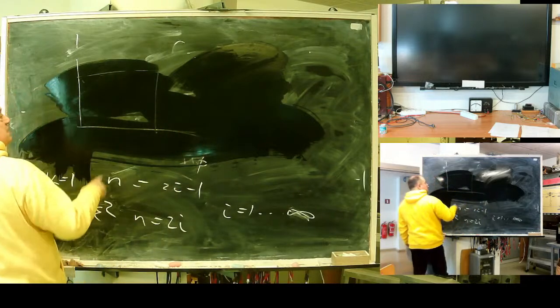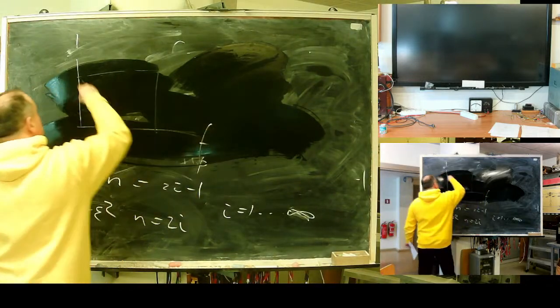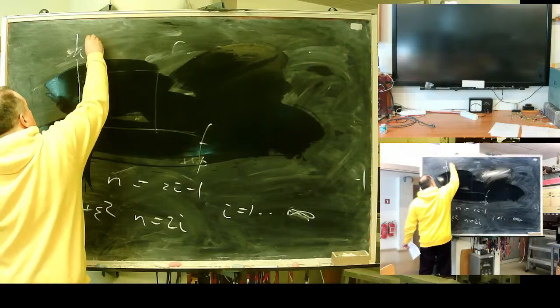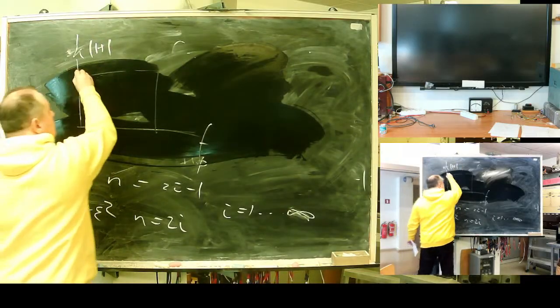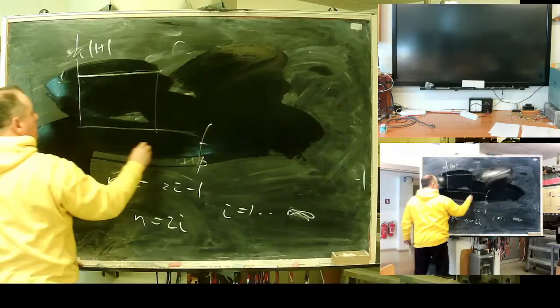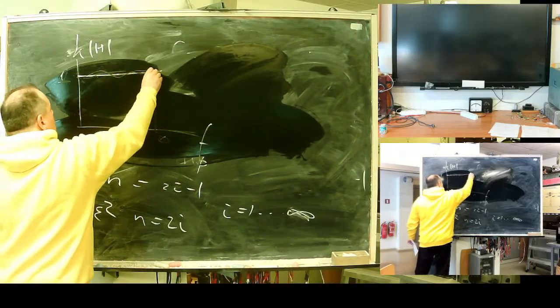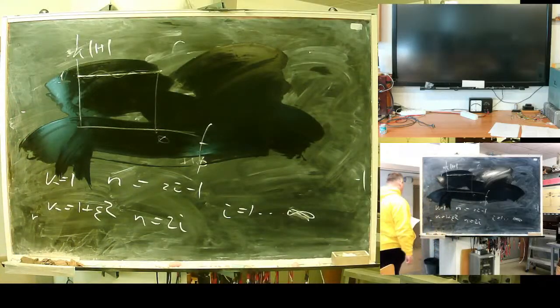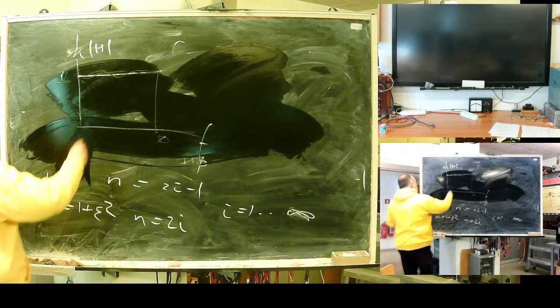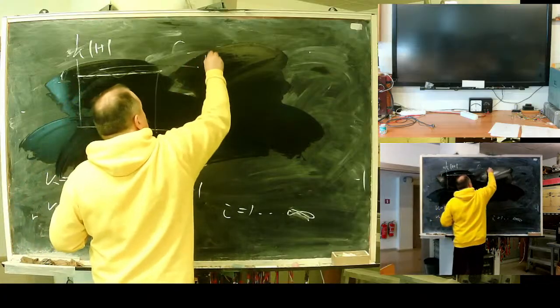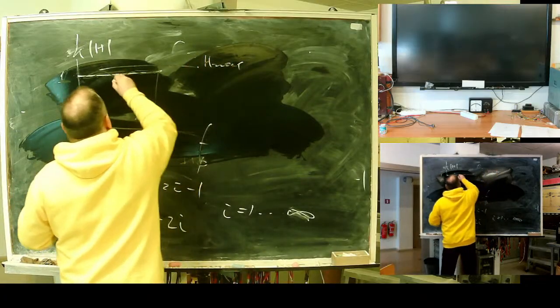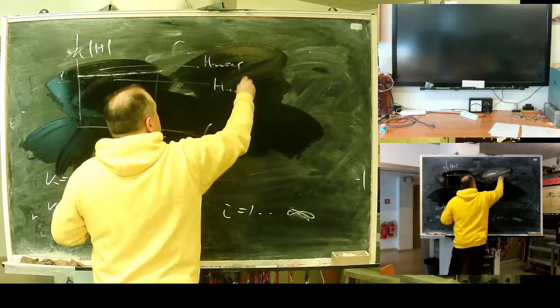the ideal characteristic is like this: frequency against the module of the transfer function. Ideal here, let's say 1, here 0. Chebyshev will give you a kind of waving. So this line will be H max and the bottom H min.